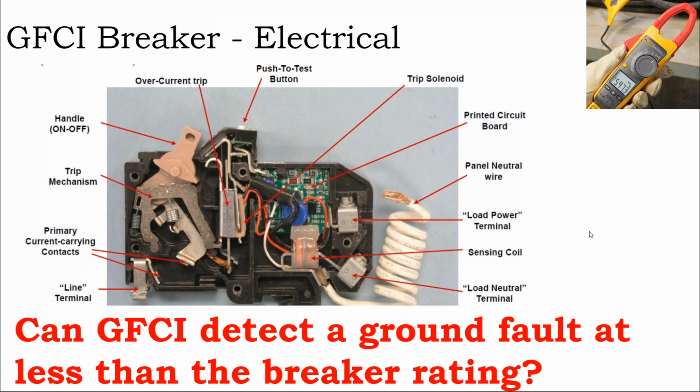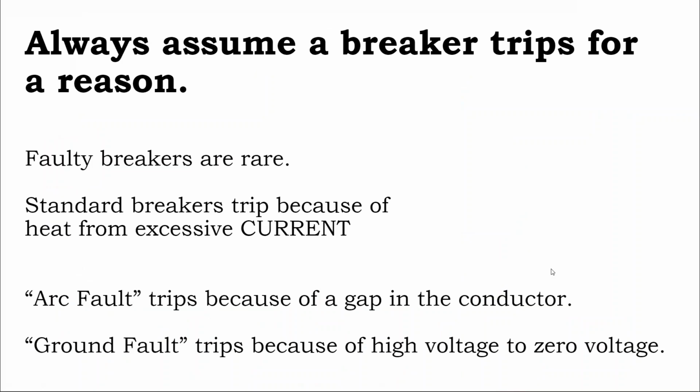So I think the important thing to keep in mind is that a regular breaker by itself is only for overcurrent. It's not for instances where it's undercurrent. It's not for arc faults. And for that reason, the inverters today are listed for arc fault detection and ground fault detection.